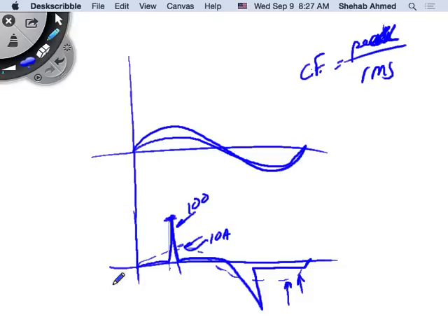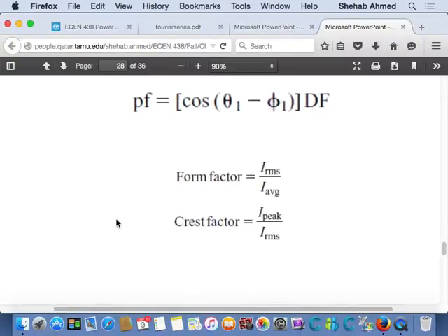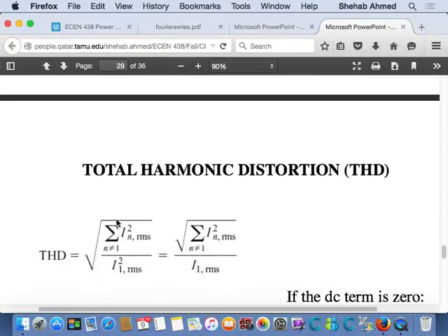So it will cause the distortion factor. It decreases your power factor, but not just that. So it increases the equipment rating because of this power factor. So on an average perspective, it increases the equipment rating. Also, on a peak perspective, when you select your components, you also have to increase the equipment rating again because of the very bad shape, the crest factor. Okay. So this is just terminology. Okay, and then next slide is the same.